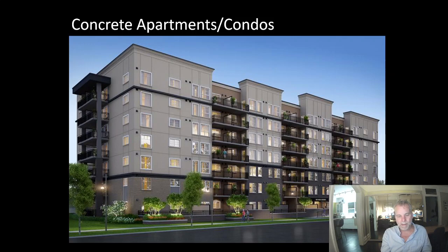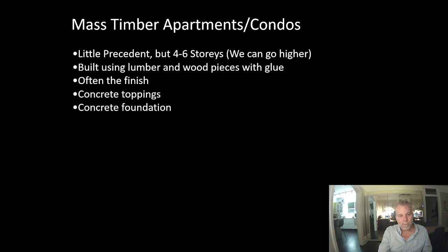break techniques. One thing we do frequently is we just put a slot. So make sure that you only have just as much concrete crossing the envelope as you need for structural performance, and that's a benefit. We also see some examples with bolt-on balconies, which can be thermally broken. So bolt-on steel balconies instead. Okay, that's cast-in-place concrete. Let's look at mass timber apartments and condos.